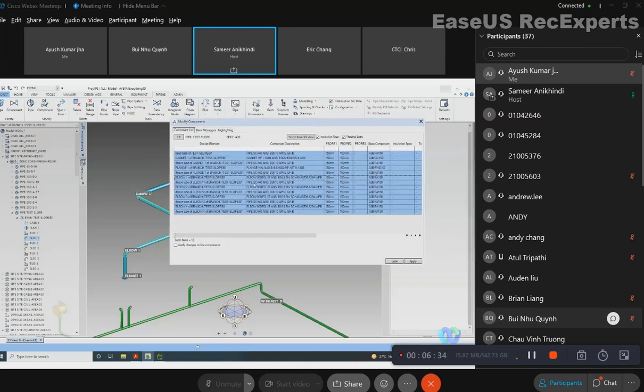And when you right click, there is a modify bore, modify specification, modify insulation spec, modify tracing spec. You can clear the selection, it will unselect everything. Select all, right? So let me select modify bore. So 150 is the bore. Let me make it 100 and click on apply.